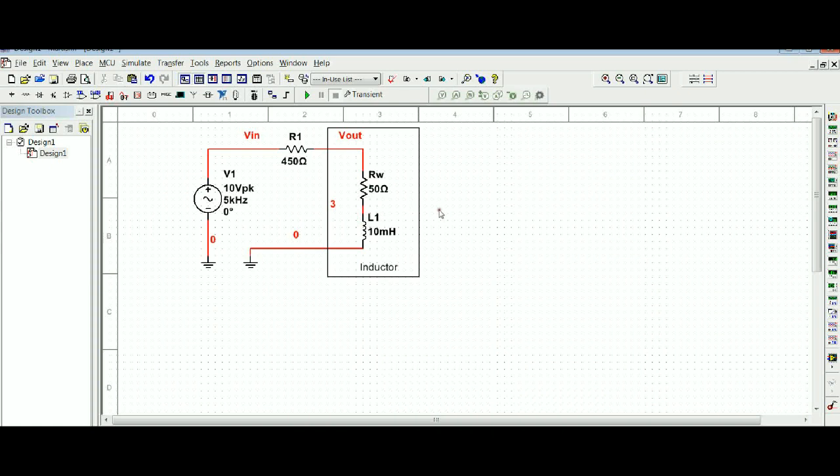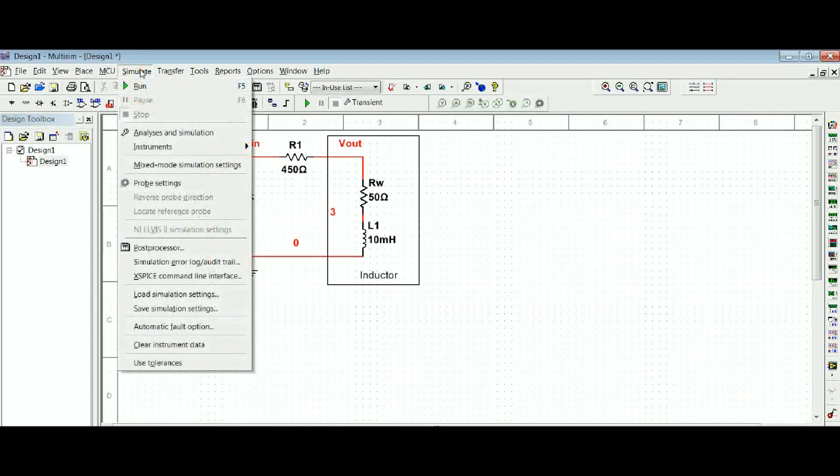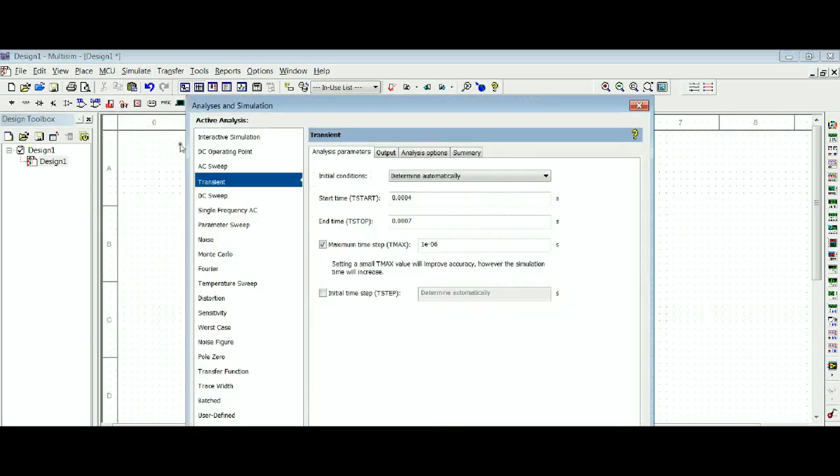Now, let's take a look at the frequency response of this, because we just did a single frequency point analysis, but some instructor might want you to do a frequency response calculation, perhaps like me, over 10 different frequencies. That basically means that you'd have to do everything we did before, and theoretically by hand, you'd have to do it 10 times. So building a spreadsheet in this is very helpful, and using the sweep on this is also very helpful. So to do that, we'll go simulate again, and now I want to go to analysis and simulation, and this time it's going to be AC sweep.